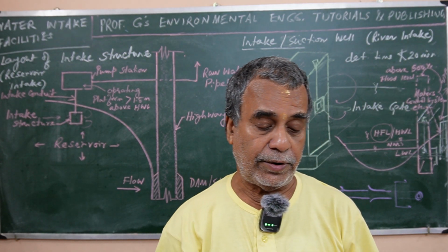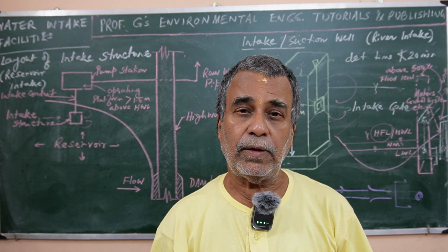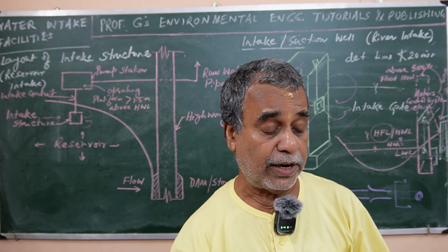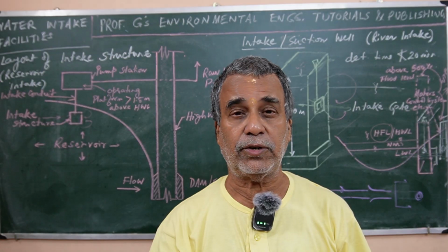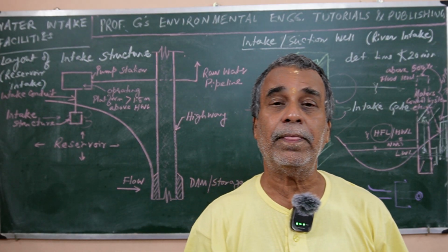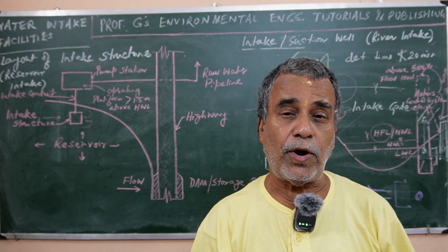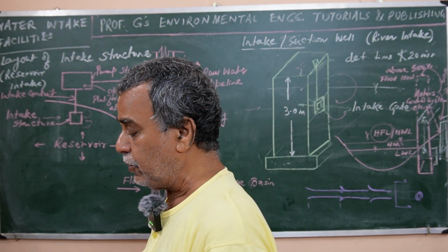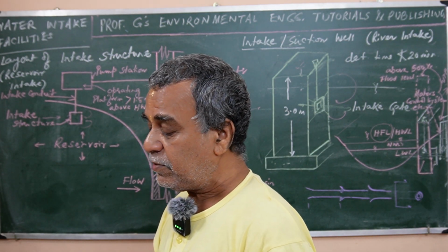So the depth and the capacity of the conduit should be designed in such a manner that the intake port does not draw air instead of water, or water with air, because that may damage the system, particularly the pumping system. Now, a velocity of 0.6 to 0.9 meter per second in the intake conduit, with a lower velocity through the ports, actually gives satisfactory results.